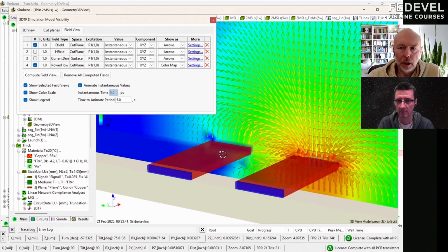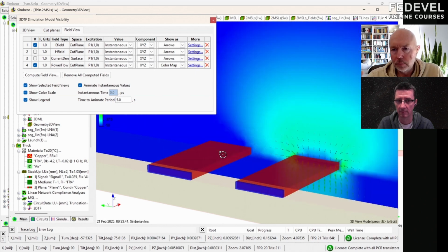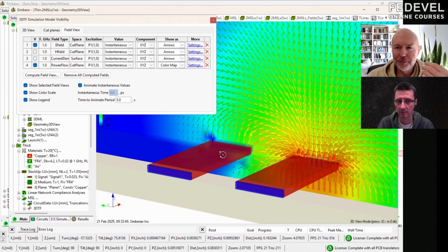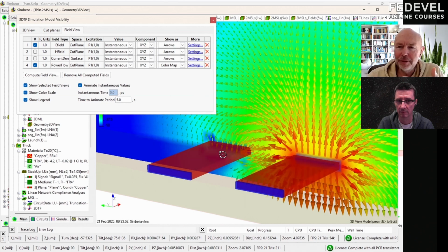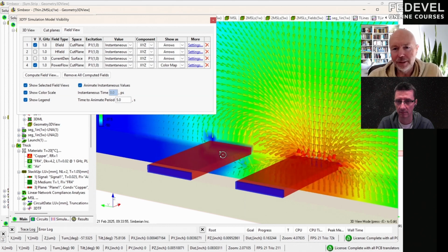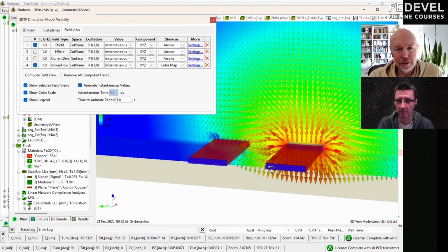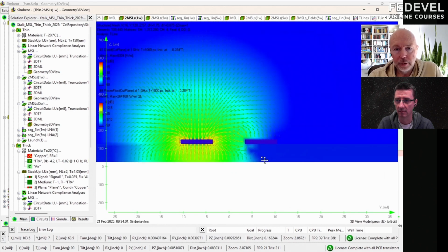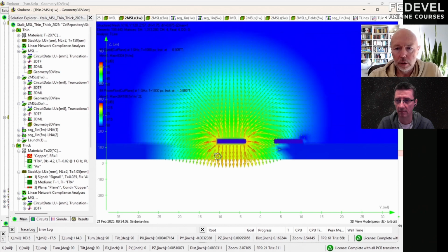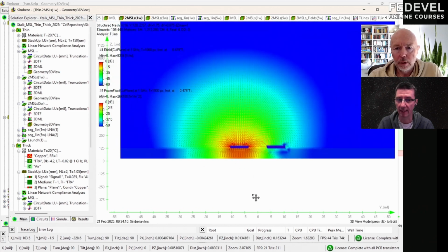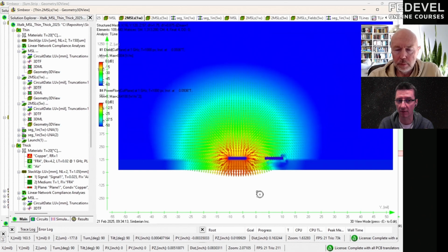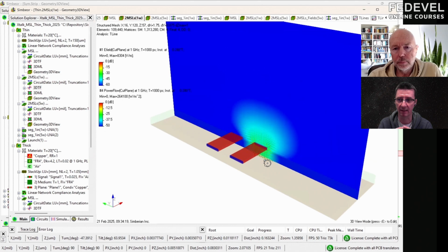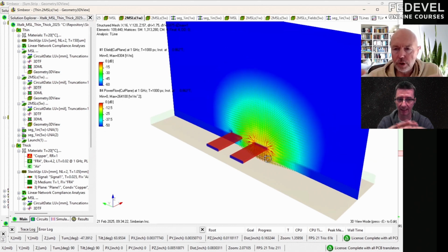Any piece of metal, other signal tracks, any unconnected piece of metal, when it is coupled, it may become an antenna. So everything that gets into this space, and right here we are looking simultaneously at the electric field and at power flow density on the same graph. But I would like to point out there are still, of course, some currents flowing through the track, but depending on frequency, they travel more and more on the outside, yes.